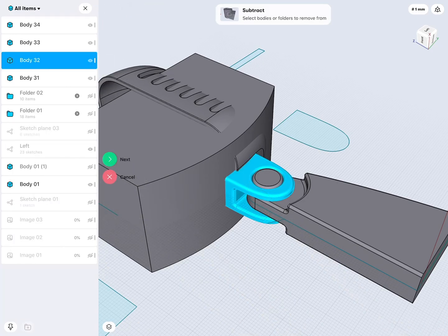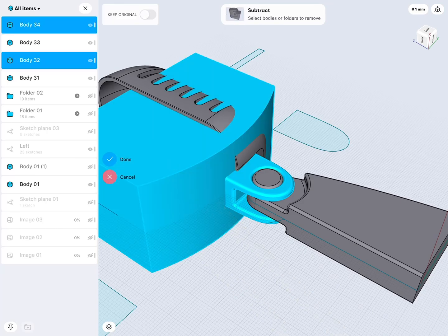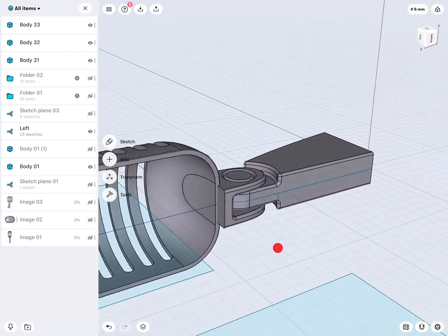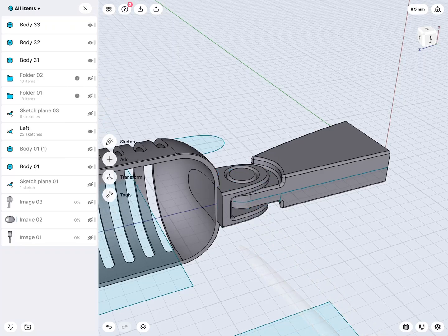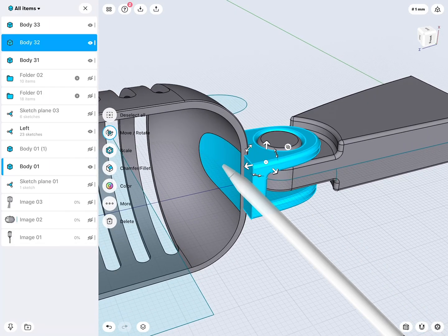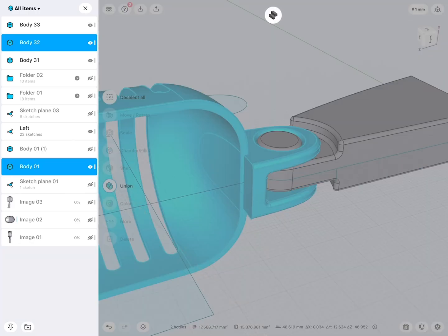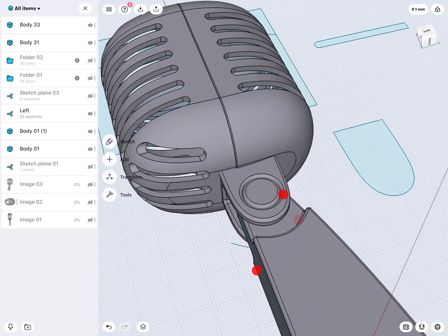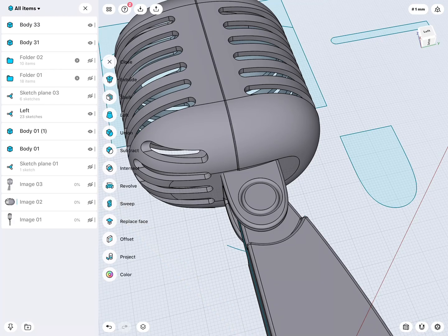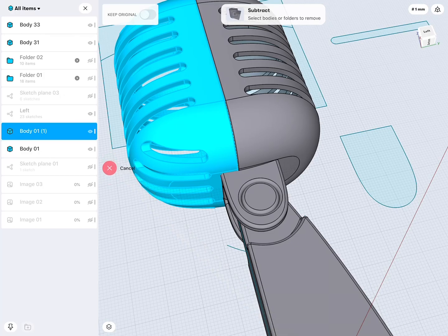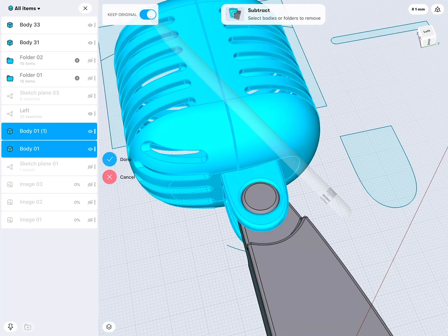Go to here, from new I would like this one to be removed. Yeah, see, this is actually still perfectly in. Very nice. Now we can do the cool following part. We say you and you join, and we would like to have an interlocking mechanism. Turn this one on and go to tools, subtract. From this one I would like this one be removed. Keep the tool however.